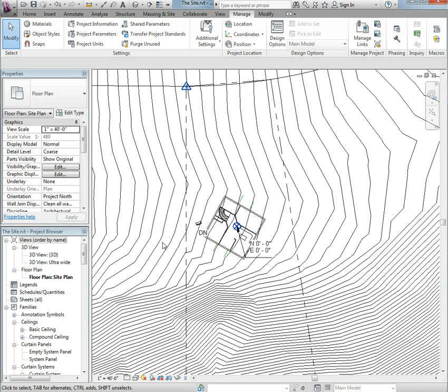So instead what you do is you create a named site in the linked file, and the named site allows you to move the survey marker to a new point in the file, indicating the new location of the house relative to the one and only real-world survey marker. So in order to do that, we can publish the same way we put this house here, we can actually do the same thing.